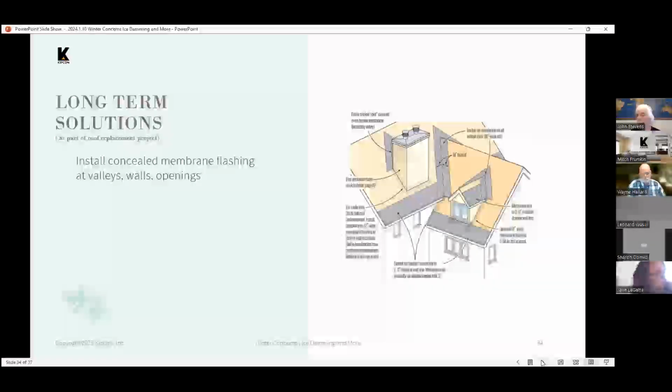And that's a calculation that we would do. If you're going to re-roof the building, we do that calculation to make sure of how much of the ice barrier you actually need. The material typically comes in 3-foot wide rolls. So contractors like just installing one row of it, because you roll it out and it sticks down and it's easy to do. But sometimes it requires more than that, and you just have to be aware of that.